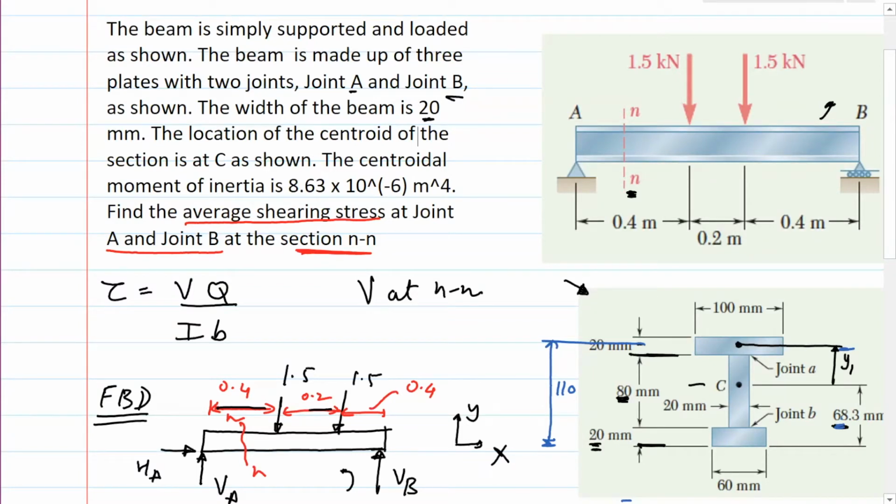My bad. When you look at the moment of inertia for the bending moment, it's the inertia of that particular section. So if there were M involved here and we're trying to find the normal stress, it will be the inertia of that horizontal section. For the shear force, it's the inertia of the complete system, which is in that formula, because it's a slightly different setup.